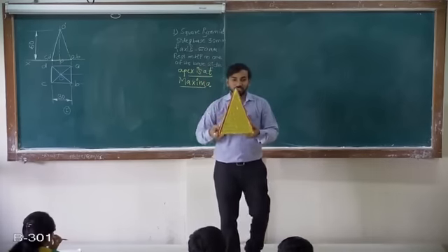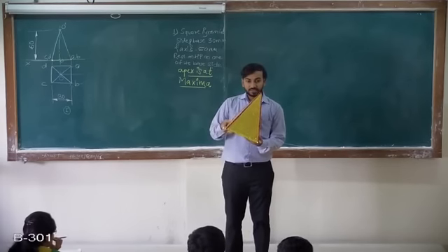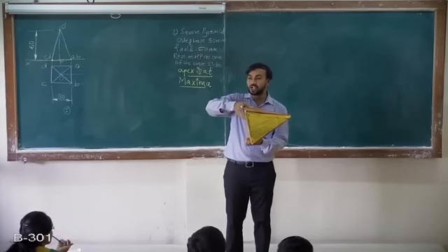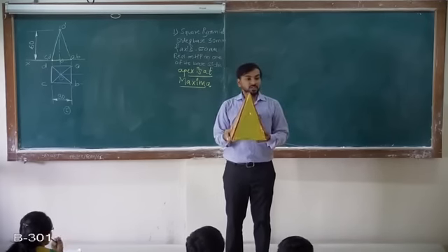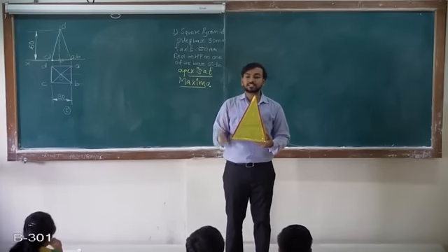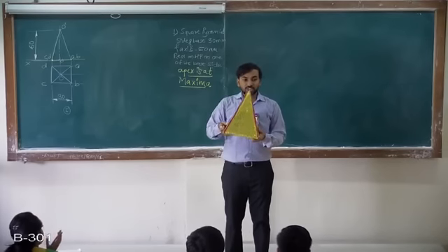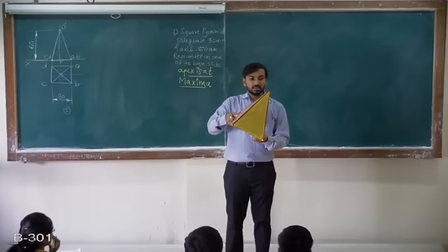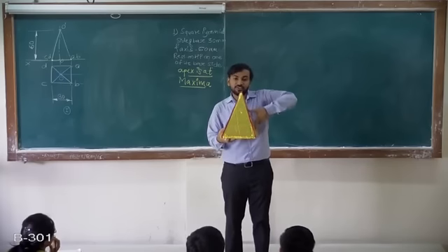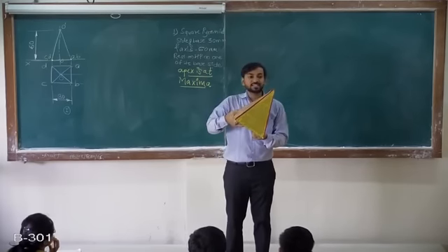You can see here the first is resting on HP, right? Now it is going to incline. Logically when it is like this, it is not the maximum position of apex. So maximum position means the apex should have the highest distance from the XY line, that is from HP. So this should be the condition. You can see this curve. When this face is exactly perpendicular to HP, then apex is at maxima.